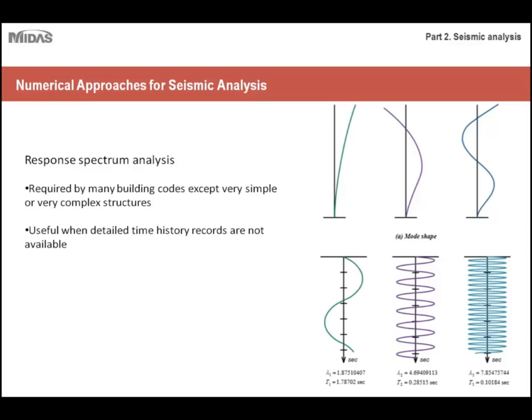I'll go into greater detail about this later, but just keep in mind that with response spectrum analysis, you don't need these time history records. You can work without them. That's particularly useful because using those time history records and implementing them is very time-consuming. It's a very detailed process.